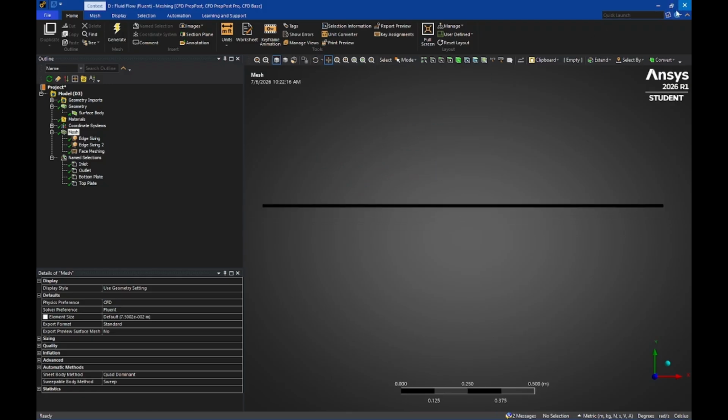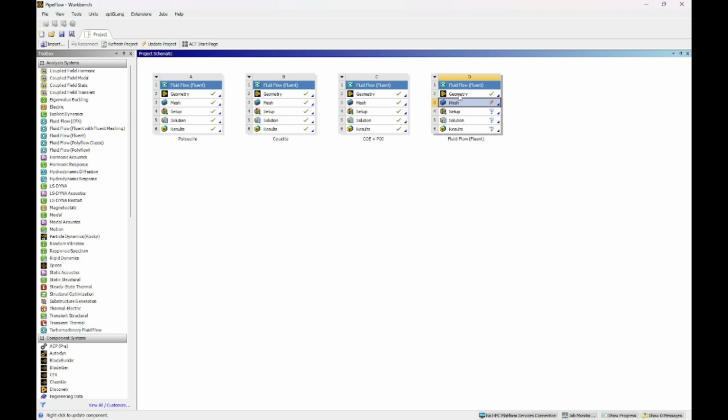Creating the mesh and the geometry shouldn't change too much between your different flows. The only reason you would need to change something is maybe your Reynolds number is too big for some of the values we need to put in the setup, so you want to change your geometry. But how you do the mesh shouldn't change. How you do the process is the same.